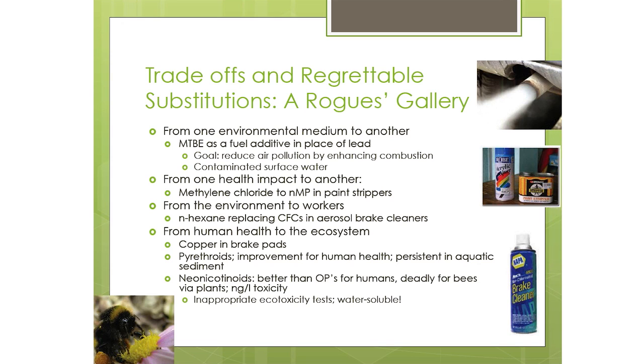The Montreal Protocol banned CFCs as a propellant, and one of the downstream effects was that we saw peripheral neuropathy in auto mechanics who were dealing with aerosol brake cleaners and breathing 7 or 8 cans of them a day, because unbeknownst to the rest of the occupational health world, we'd replaced CFCs with n-hexane, which was actually known as an occupational hazard in other occupations, but not in this particular one.